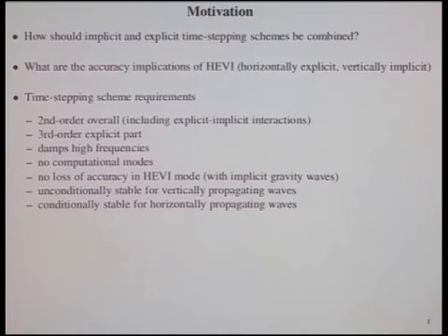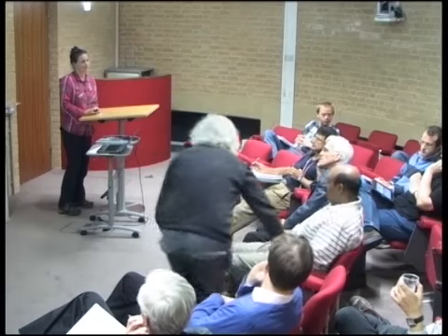Todd: I hesitate, but I must. The whole reason to use implicit is because there's something that you want to step over. If the thing that you're trying to model is important, it should be explicitly time stepped. And so am I wrong there? What's the motivation for implicit time stepping if you're not willing to degrade your accuracy at all of that process?